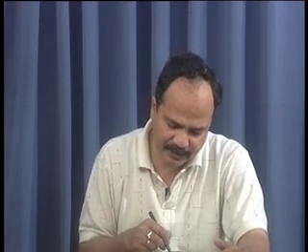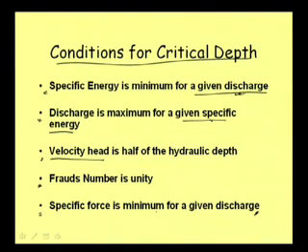But still, the relation we will get is that specific force is minimum for a given discharge. So both specific energy and specific force are minimum at critical condition. These are some of the important points that we have derived.